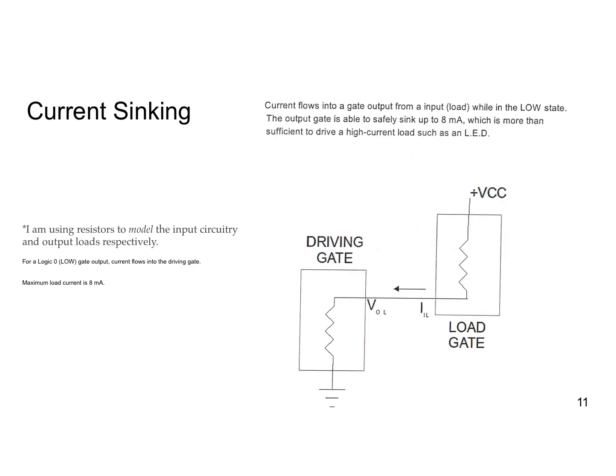Current sinking. You can think of current sourcing as pouring water out of a container. Current sinking is pouring water into a container. That's a silly little analogy I use to remember it. But again, modeling the gate internals as just resistors, current sinking goes like this. Current input low, maximum. Negative, and that's just because of the current direction flowing in. It's assumed to be negative.